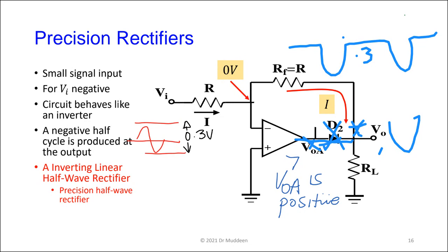But because the diode is in, for the diode to be operational, if RF is in, here has to be more positive than here. Right. So if here has to be more positive than here, in terms of a negative voltage, here can't be positive. It has to go below 0 for this diode to be on. So that's why it's actually tracking the negative half of the cycle and not the positive half, just because of the diode.